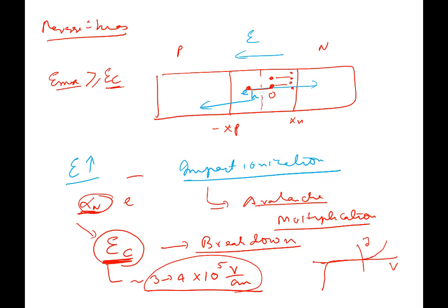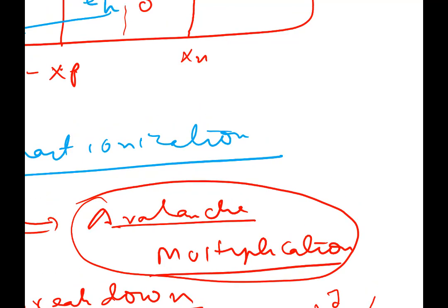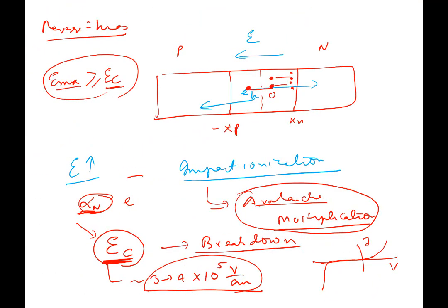And we already know how to calculate field. Given any PN junction, we saw how to sketch the electric field, voltages and all of that, how to calculate field, we already know. So the essence of breakdown is this. In almost all PN junctions, breakdown will occur by an avalanche multiplication process. Only if you go to a very specific junction which is P plus, if you go to a junction which is P plus and N plus.